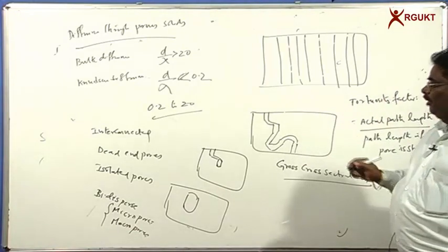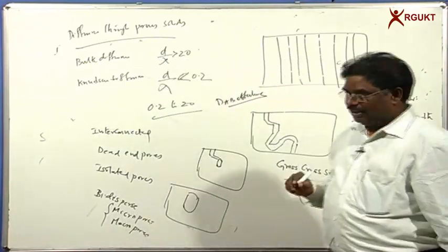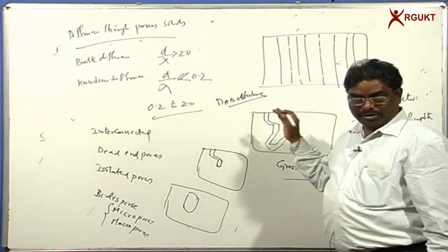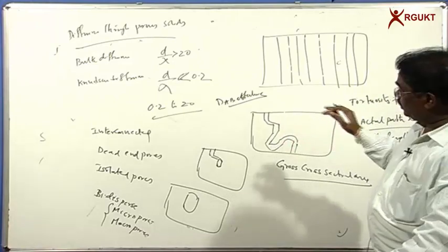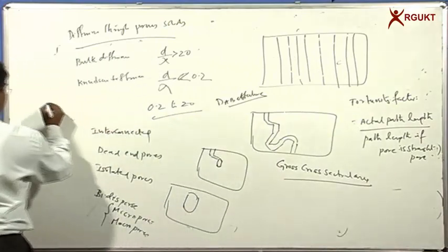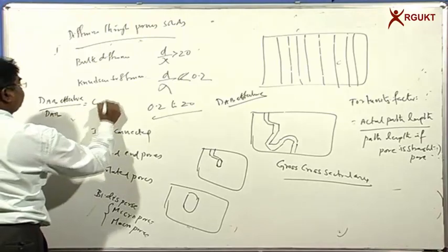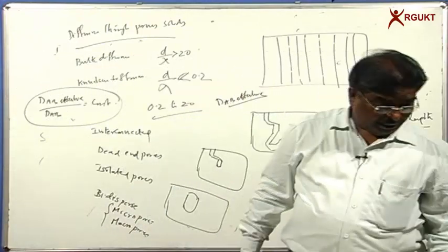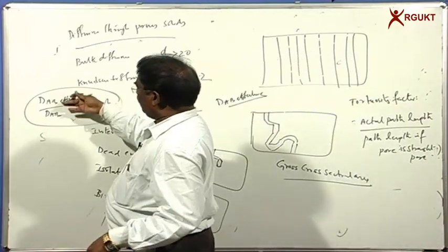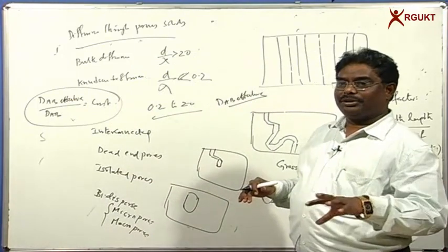And that is the reason we have a parameter called DAB effective, and this DAB effective is very small compared to the actual DAB values. For a given solute system, DAB effective by actual DAB will be a constant, or one can say DAB by DAB effective will be constant, and this will not change even if you change the solute.